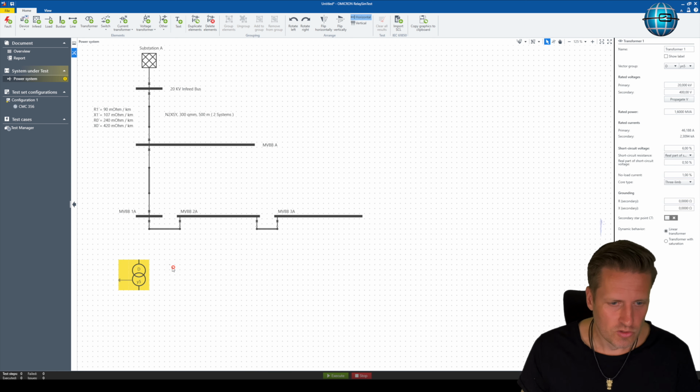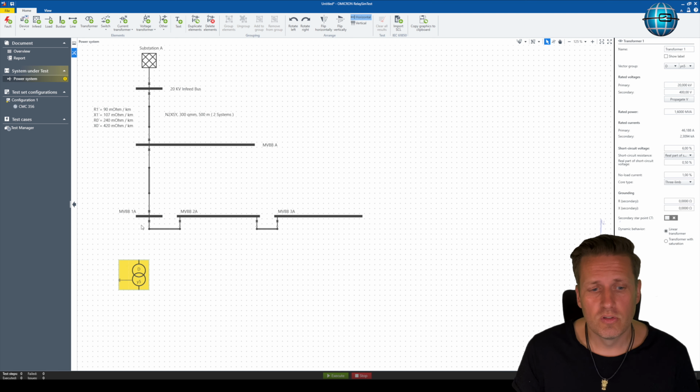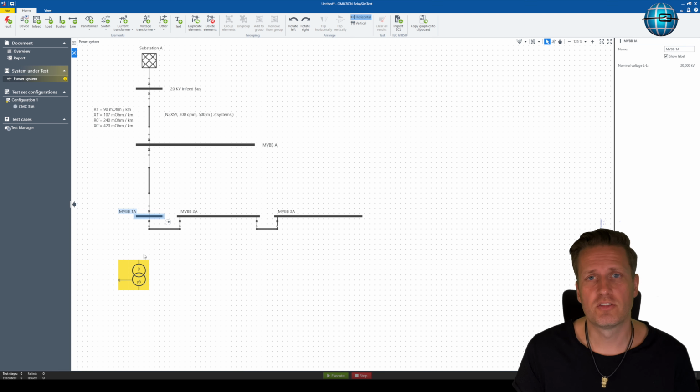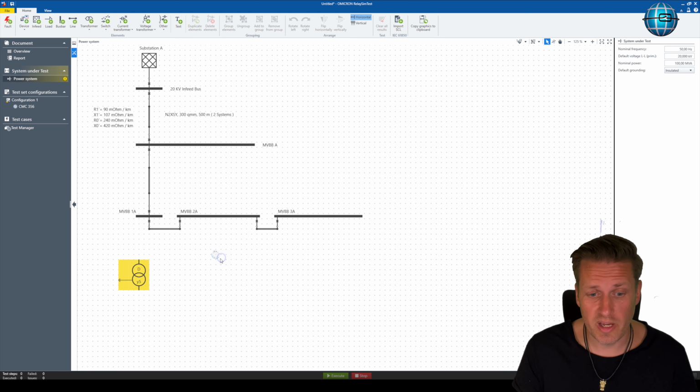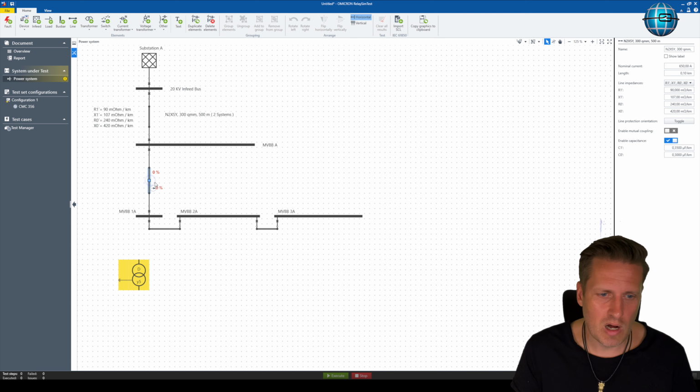Okay, so now we want to connect this transformer to this bus bar via cable. We need a line model because we always have a lot of capacities due to these cables. It of course depends on the length of this cable. So let's take this line model again, but we can also use our model that we have, and we don't have so much work.